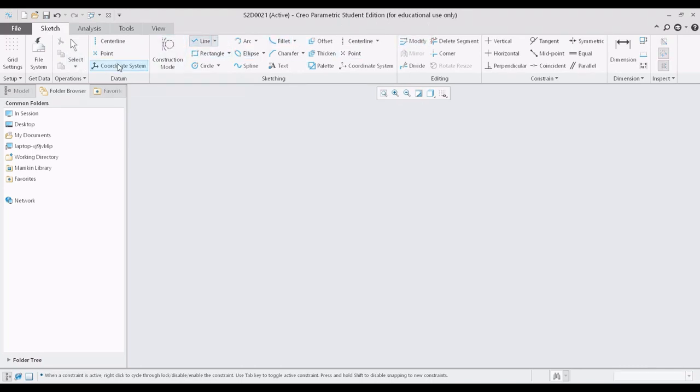If I have a coordinate system and a line originating from the center and stopping at this particular location, and the distance is something around 150. Generally if I want to modify, so far I am using a technique of double clicking on the dimension itself and modifying the dimension as desired.